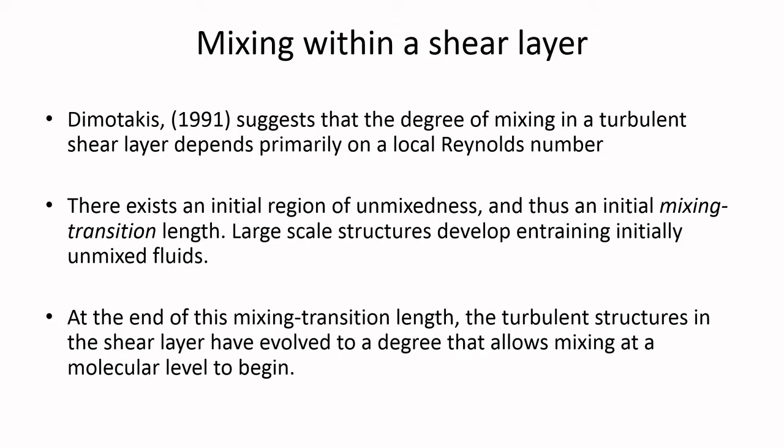The reason is that in this region, large scale structures develop and they entrain initially unmixed fluids. The large scale structures roll up and create strain on the fluid elements, and essentially create large gradients through which mixing can happen. But that takes some time to develop.